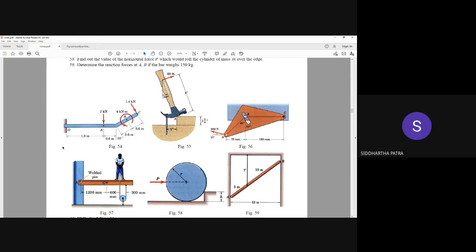Without a fixed joint, you cannot apply so many loads and expect the body to be in equilibrium, which basically means if you write down all three equations of equilibrium, assuming only two reaction forces, you will have an inconsistent system.